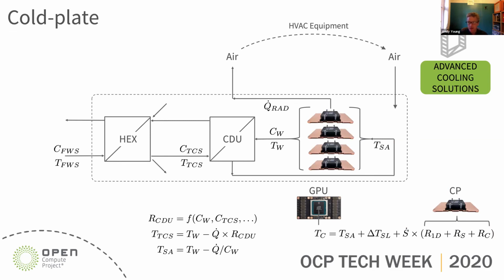In comparison, looking at cold plates now, it's a different picture. So now the air heat dissipation route is there in parallel, and we get feedback. So you can see this by having a tightly integrated cooling solution. So the spreading and thermal resistance due to convection are closely coupled to the IT platform SKU.